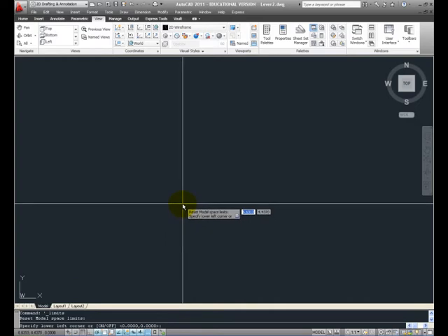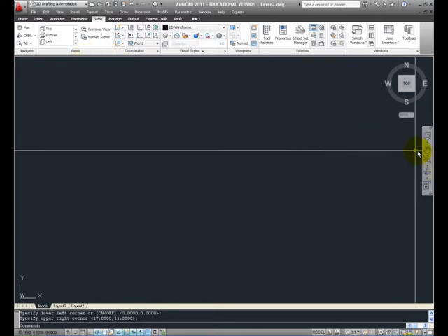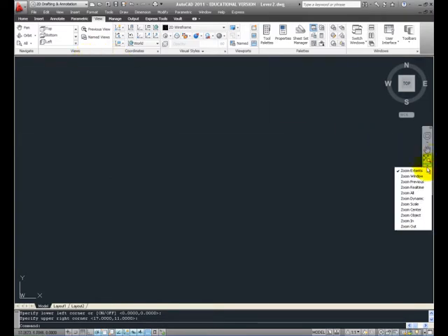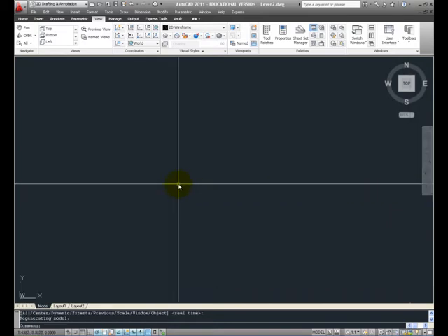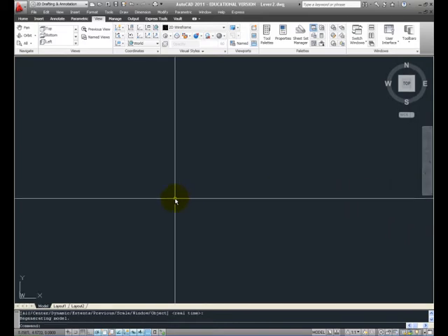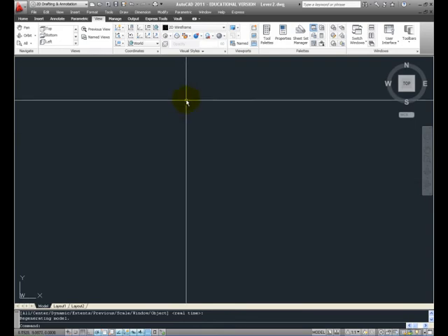You'll notice that our drawing limits have a lower left corner coordinate of 0, 0, and the coordinate for the upper right hand corner I've set to 17, 11. Let's do a zoom all, and we'll start out by drawing a circle.